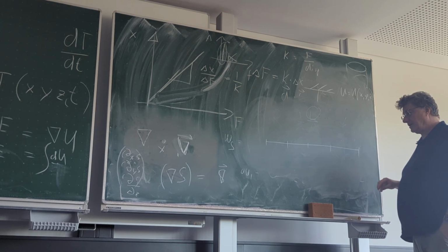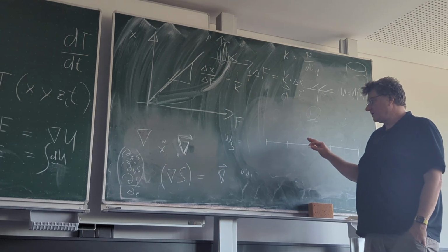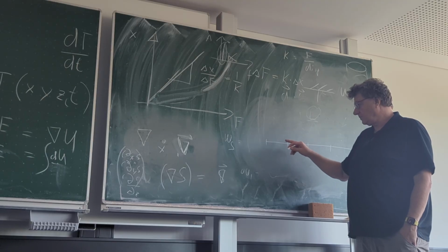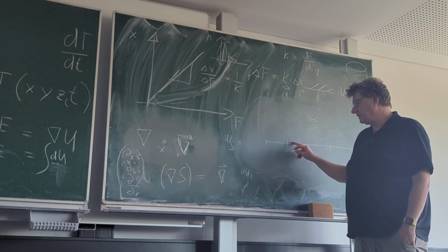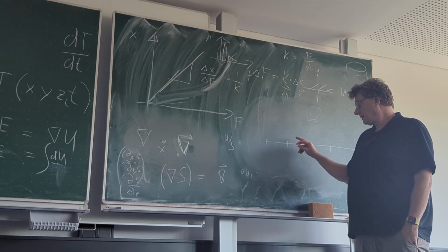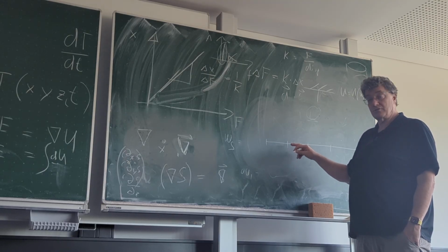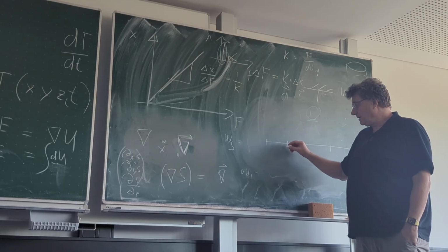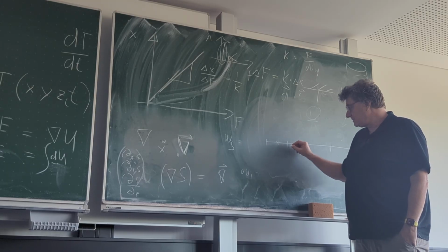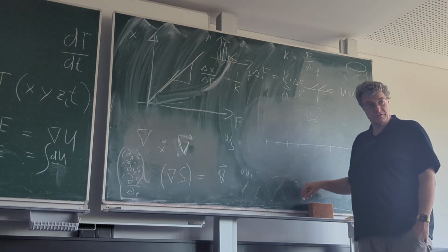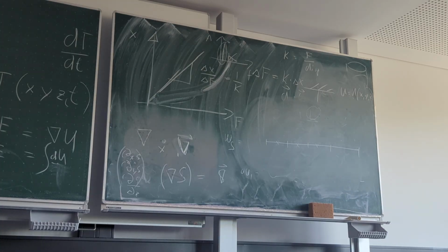So the question is, what is COMSOL doing particularly for the values in between? That depends on whether it uses first order shape functions or second order. If it's second order, it has some invisible in-between mesh nodes where it would calculate values. So let's check what COMSOL is using.